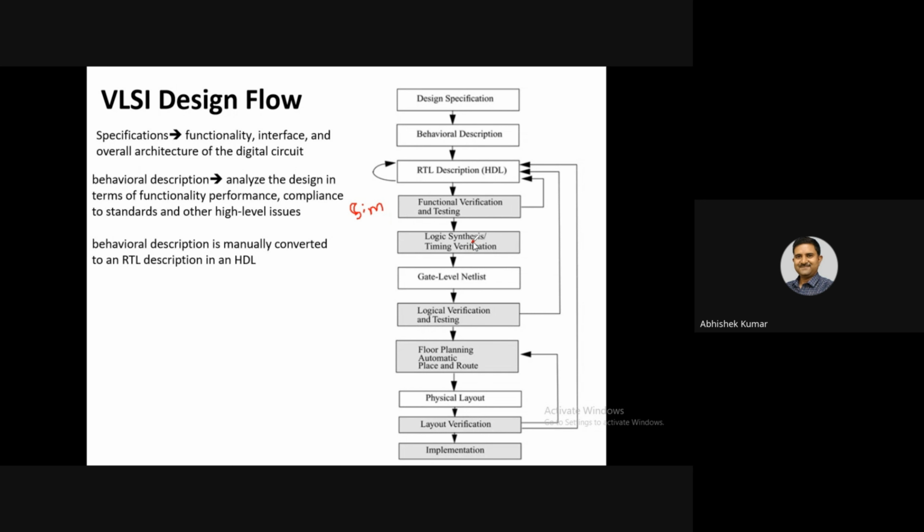But we will see in the future that there are certain steps for which hardware is undefined, for example the modulus operator and the exponential function. For these components and operators, hardware is not defined directly. So we have to use another approach, known as the lookup table, or LUT, approach, to design the equivalent hardware.